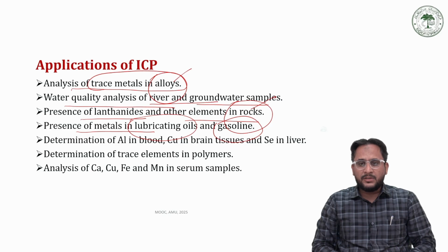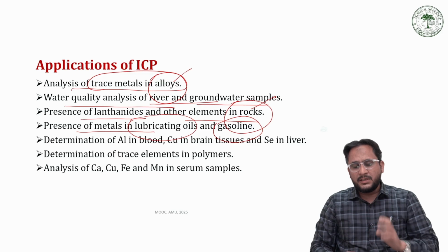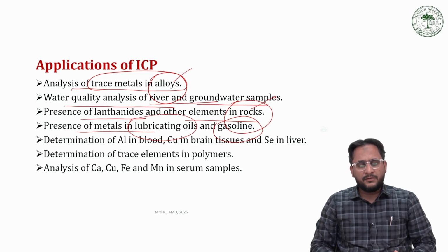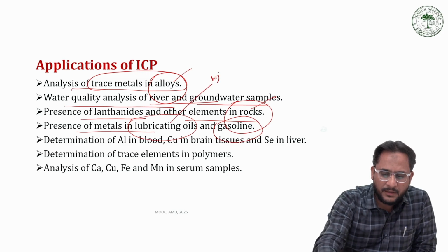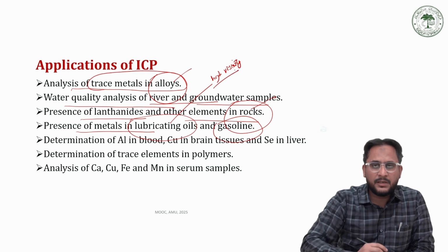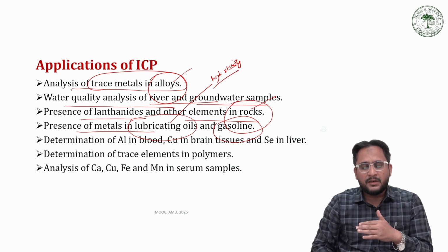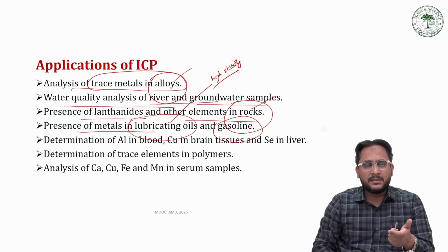For that, we can take a gasoline sample and filter it. Although gasoline viscosity is not high, we can use it directly. Lubricating oils have very high viscosity, so we can dilute these lubricating oils using some solvent to minimize their viscosity, and then we filter it, and finally we can analyze it by injecting it into the nebulizer,